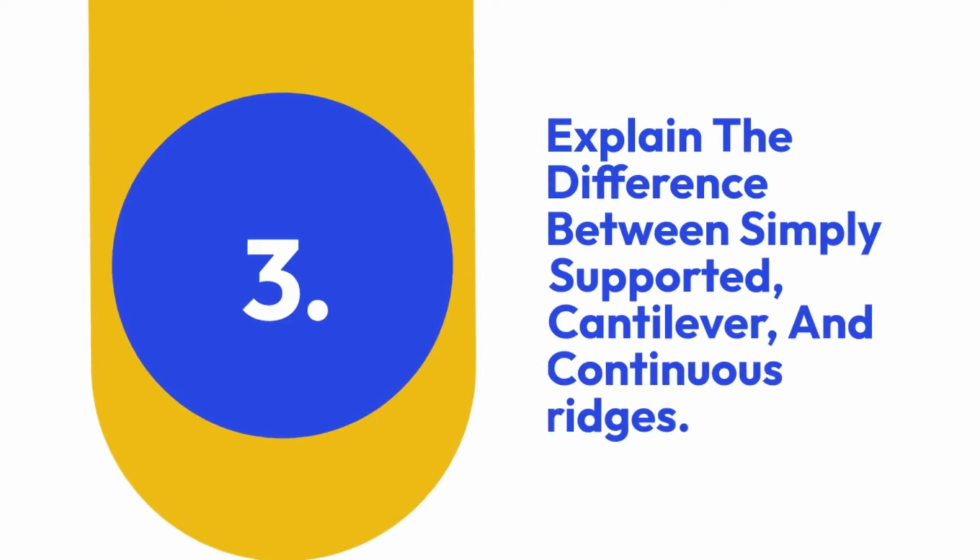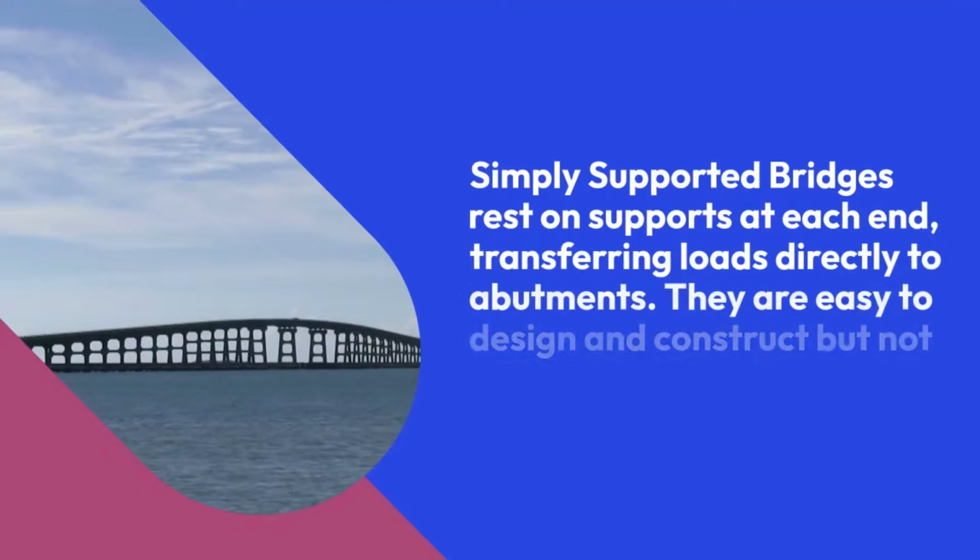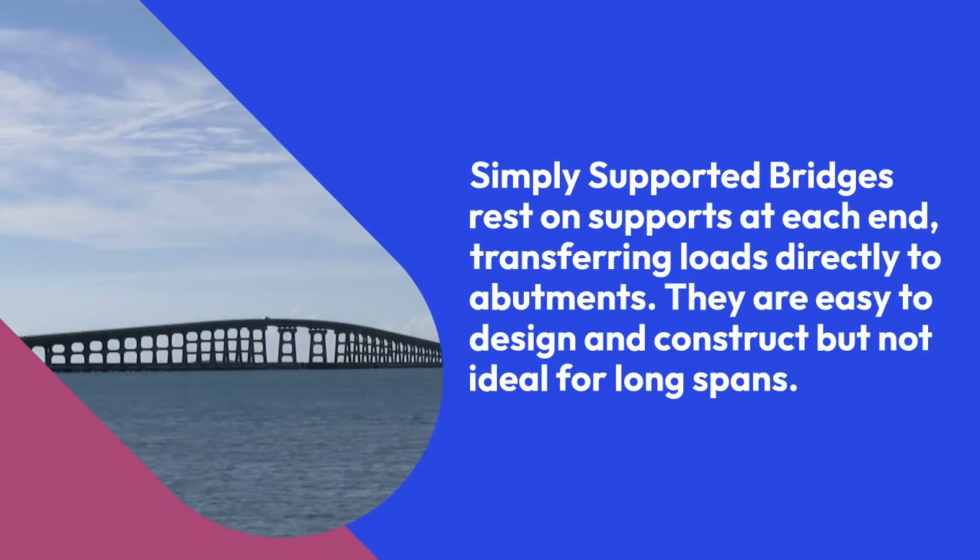3. Explain the difference between simply supported, cantilever, and continuous bridges. Simply supported bridges rest on supports at each end, transferring loads directly to abutments. They are easy to design and construct but not ideal for long spans.